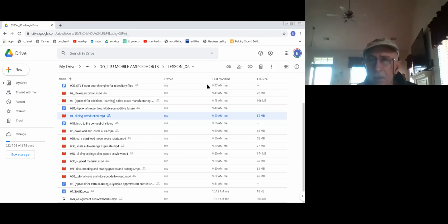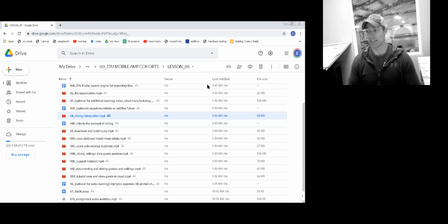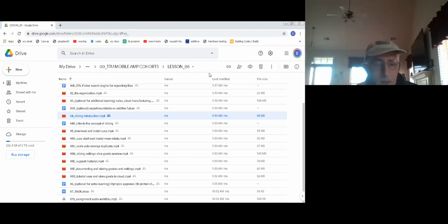Is there a header in the G code that tells what printer was used? It depends on the slicer, whether they put that information in at the top. A lot of times it's just generic. I haven't studied a whole lot of the code outputs. You do see a lot of text information that is semicoloned out at the top that gives some of the basic settings. More than likely it's in there somewhere. We would just prefer them to say, hey, if you wrote it for the Sidewinder or the Genius, make sure we know it in the actual file name. But most of these G codes are very generic. You can open them up in a text document and see what they're saying. All right. That's a good question.